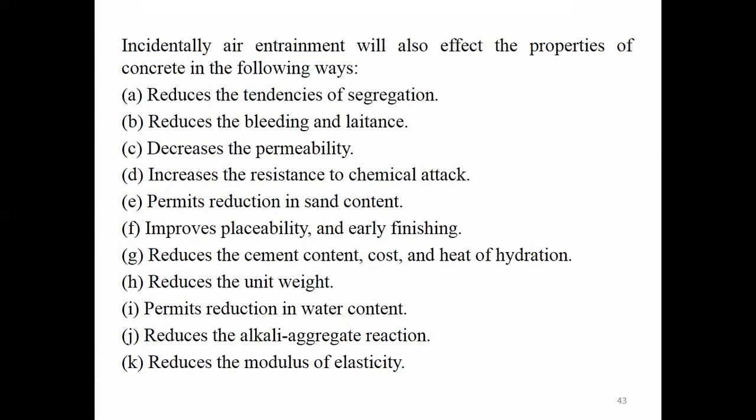In addition to this, there is one more point, that is abrasion resistance. Concrete containing less than 6% air entrainment has about the same resistance to abrasion as the conventional concrete. So whenever you are adding air entraining admixtures, if the amount of air entrainment in the concrete is less than 6%, its resistance to abrasion will be the same as the conventional concrete.